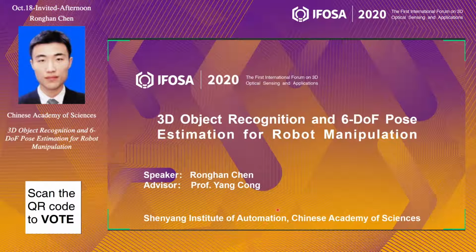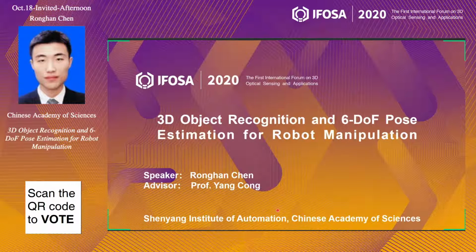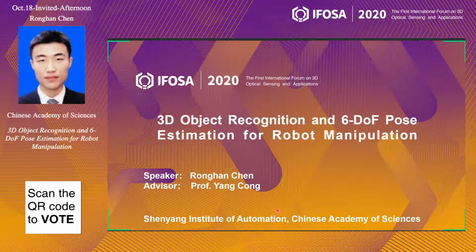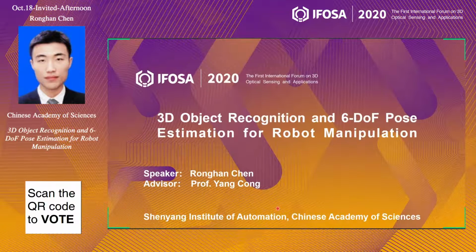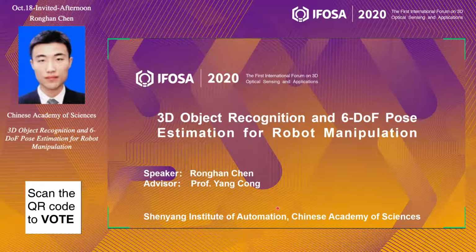The vector x, y, z here specifies an axis, and the angle theta is the angle that rotates around the axis. And the quaternion is an extension of complex numbers and can also be seen as a 4D unit vector composed of qi, qj, qk, and qr. Together, the pose is 6 degrees of freedom.